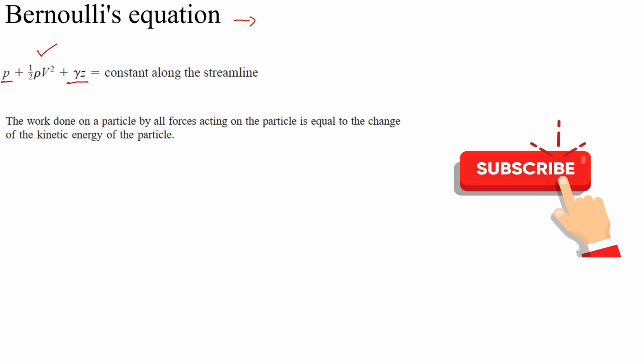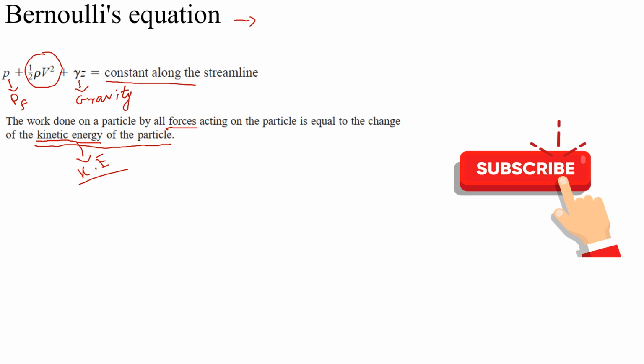The Bernoulli equation can also be defined by this statement: the work done on a particle by all forces acting on the particle is equal to the change of kinetic energy of the particle. Here they are talking about forces. So what are these forces? These are the pressure forces, the forces occurring due to pressure, and the forces occurring due to gravity. By changing these two forces, we can change the motion of the fluid, and as you can see, this motion is represented by the kinetic energy term. Overall, this will be constant along the streamline.